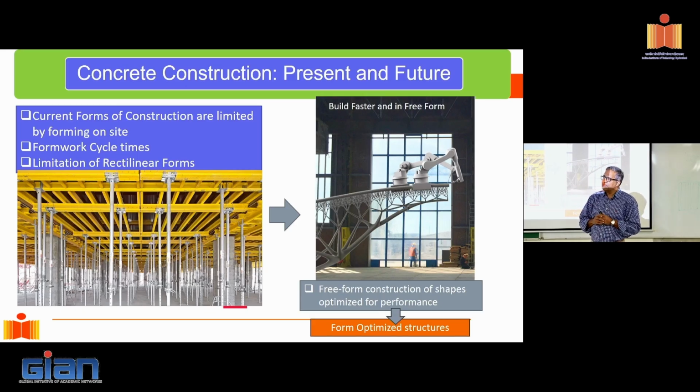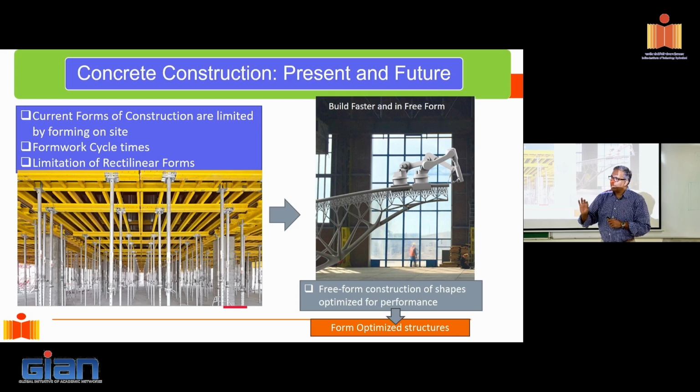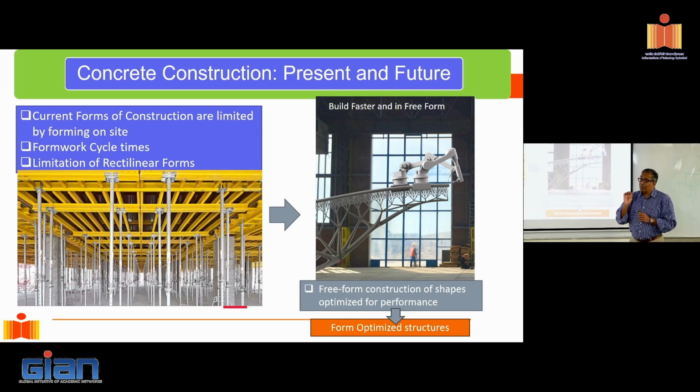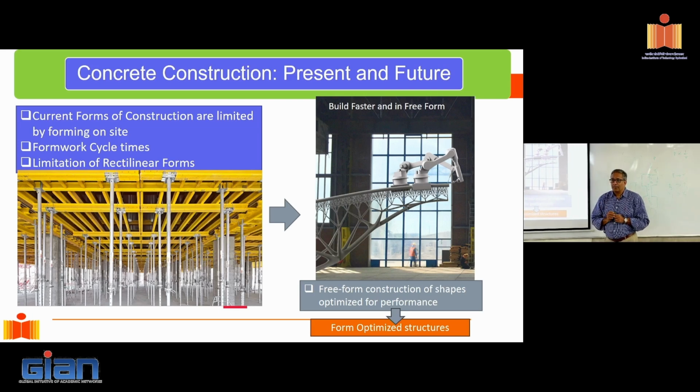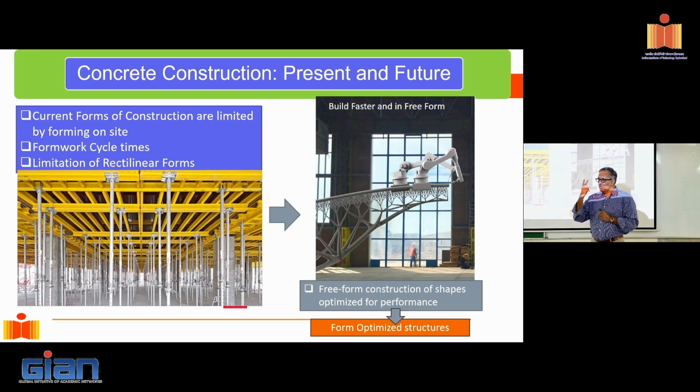How can I improve the efficiency? Well, first thing is, do I need it to have a uniform cross section? I can take away material from the web part of it, create an I-beam, and that we know is structurally much, much more efficient. It'll give you almost similar stiffness and almost similar capacity for much less use of material. Now, what is that extra material doing that is sitting in the rectangular beam? Two things. One, it's adding to weight, right? So what is the consequence of this?